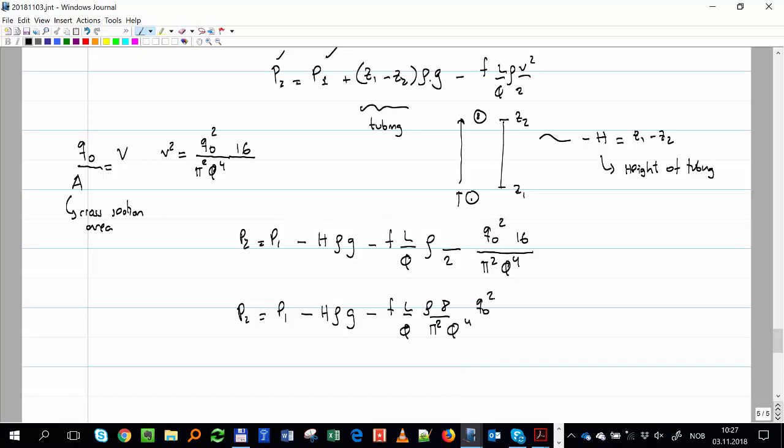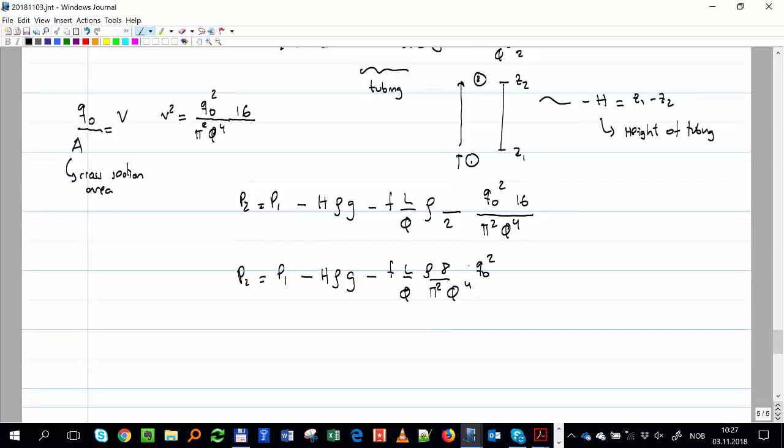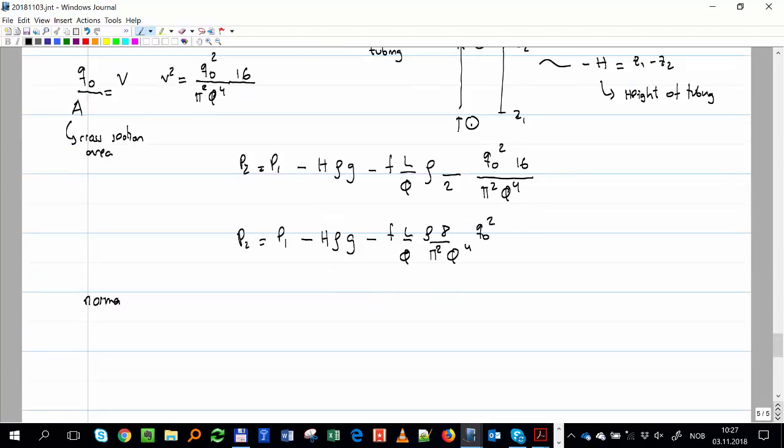Okay. Of course, here we're making some assumption. Okay, we normally work with QO, right, at standard conditions. And you know, the reservoir rate is just BO times QO. Okay, but in all of this development, we are assuming that BO is very similar to 1 for this development. If not, you have to make it in sections, okay?